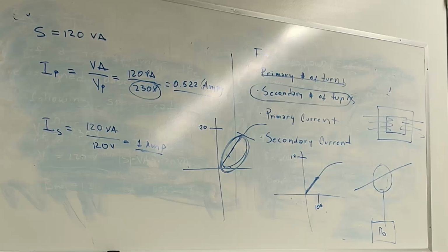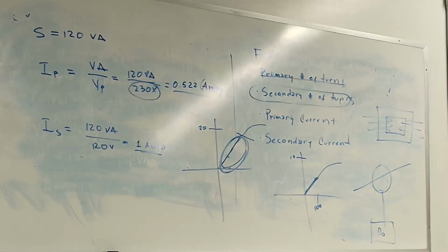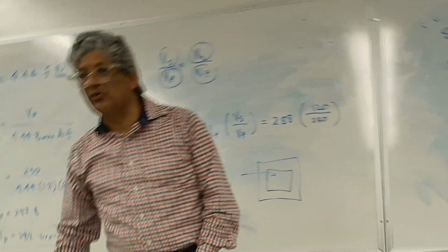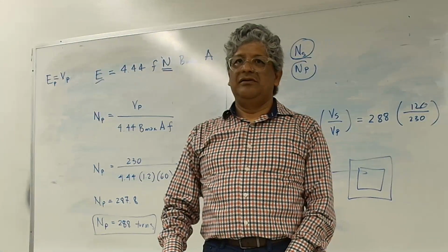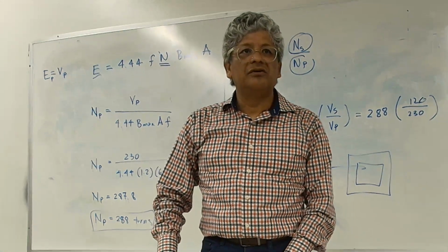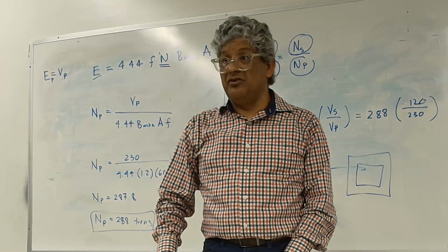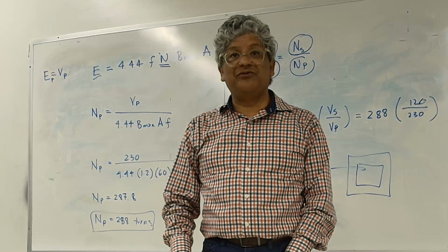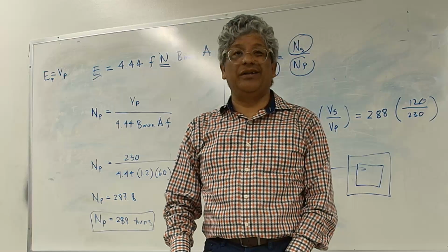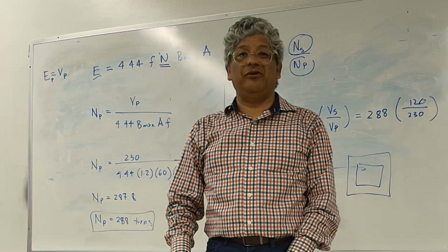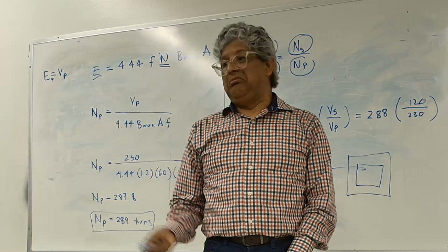I'll give you another one. Instrumentation transformer, there's also revenue transformers. That's what you have at your house. You have a revenue transformer. That's where the utility is charging you. So that transformer, who cares? I don't care whether it saturates when there's a fault, because it's going to be cleared.